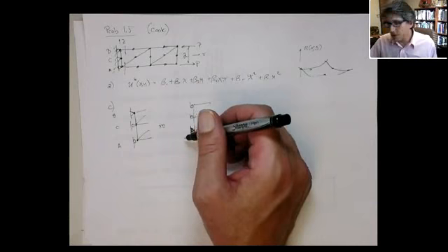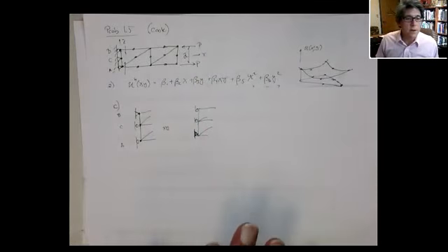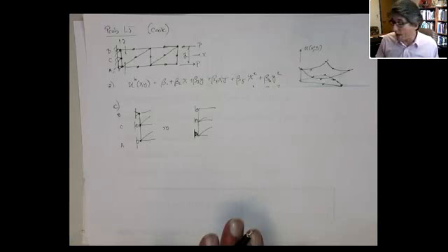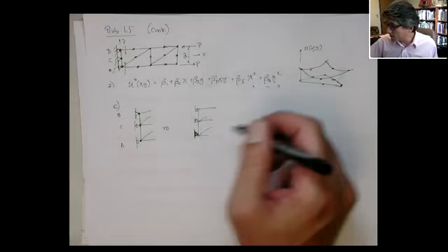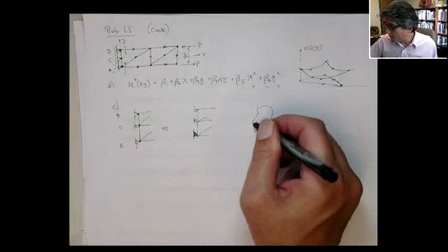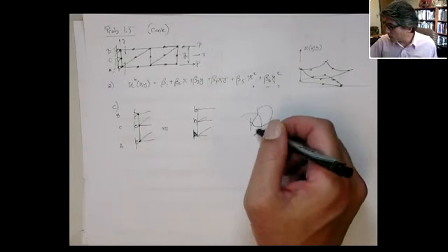The other way you want to think of this, and we'll talk a little about this later on as well, is you want to minimally constrain it to reject the rigid body modes. Now this is a little more than that actually, but you pin one point. As soon as I take a body and I pin one point, it can't move in X and Y, but it can rigidly rotate.